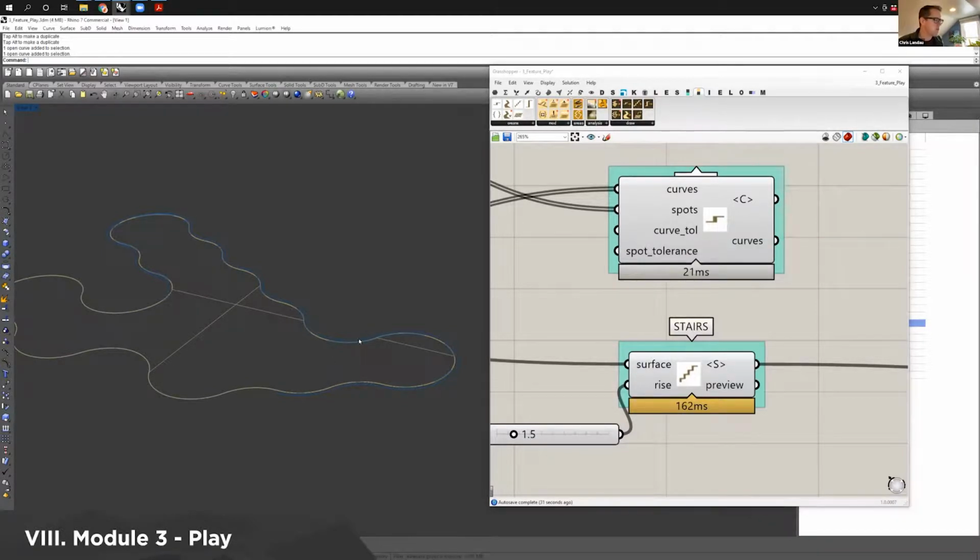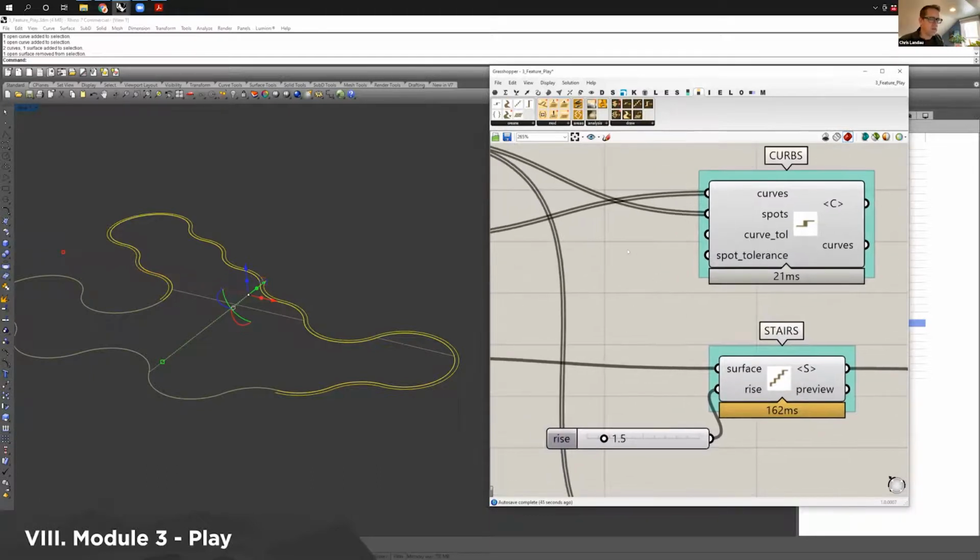That means it's going to pair these 2 curves together as long as their center points are under 2 feet apart. Sorry about that. So if I said 0.5, it wouldn't pair them. Or if I said less than 0.5, which is the offset right now, it wouldn't pair them.